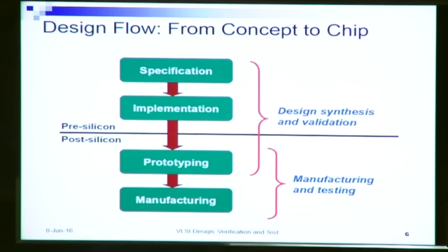Specifications are done by, let us say, hardware description languages like Verilog, VHDL, SystemC, etc., or even at a higher level, architecture description languages like, say, LISA, for example, and can also be done through graphical tools like, say, SpecCharts or SpecC, etc. And then such a specification will be taken in steps to the final implementation.